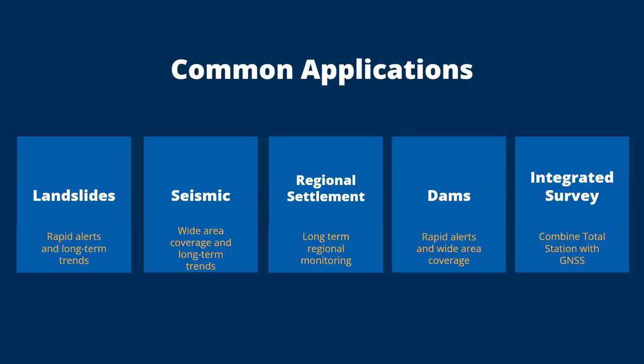And actually, if you want to learn more about how the base station location is treated as fixed and the monitoring locations are treated as floating and kind of do that least squares adjustment, you can go back and watch the previous webinar. It's the same math and the same adjustment process. It's just a different method to collect.